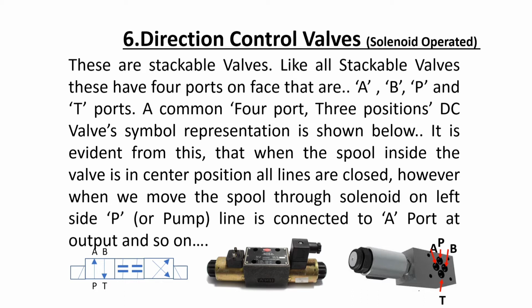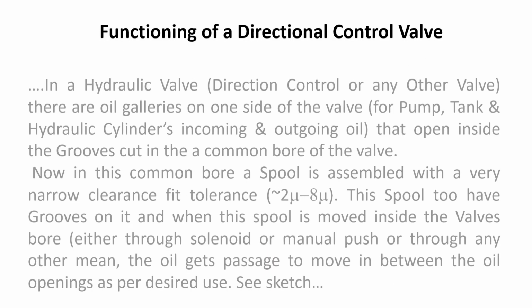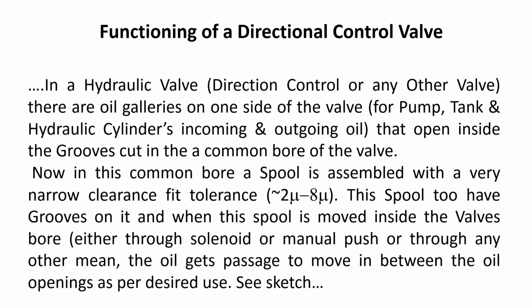It is evident from this that when the spool inside the valve is in center position, all lines are closed. However, when we move the spool through solenoid on the left side, the P pump line is connected to the A port at output and so on. Similarly, we can have a central position, we can have a right position also. Functioning of a direction control valve.